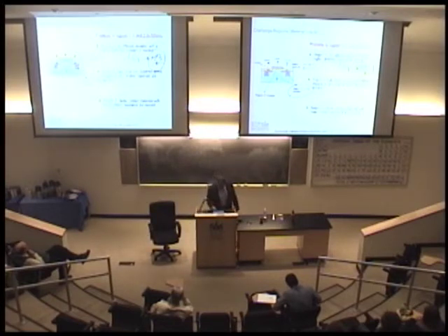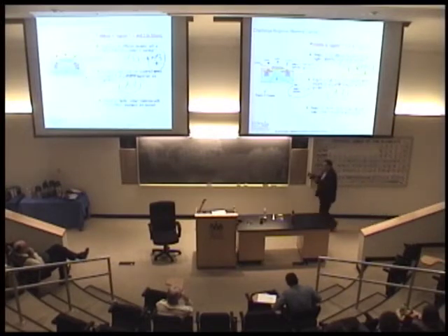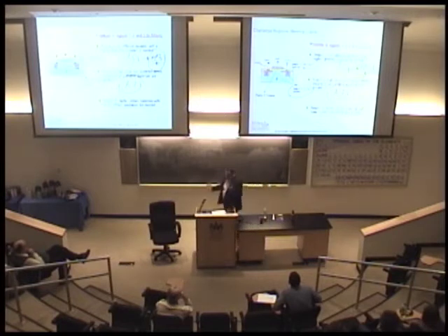So the second challenge region is how to dope very high concentrations of arsenic and boron in very shallow materials, okay? In something like 10 nanometer thickness, how do you put in more arsenic and boron? Because arsenic has one extra electron, it will give you an extra electron. Boron has one less electron than silicon. That will be a hole, and that will be an electron. These are the extra charge carriers that we use to increase the conductivity. So you can use boron and arsenic. You see that symmetry between them. And the problem is if you put in too much arsenic, then you're in trouble.